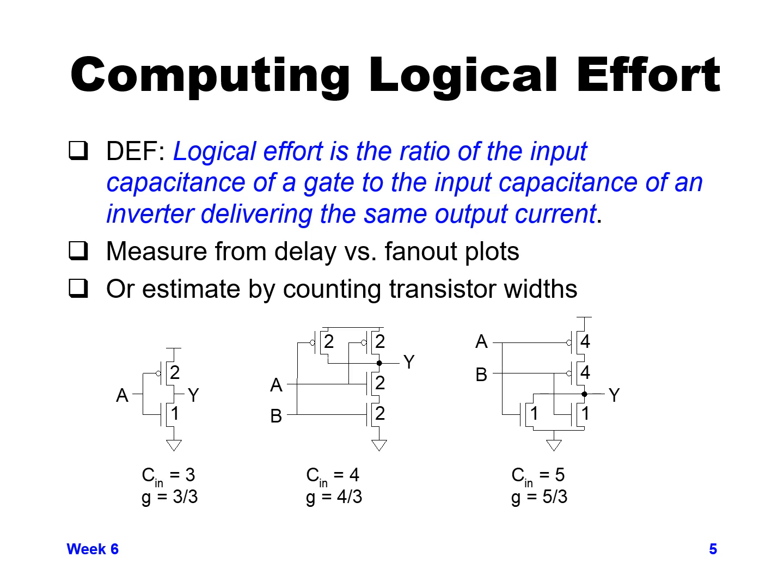So that's why the NMOS are twice as large, but the PMOS, since they're not in series with each other, each PMOS can drive independently to the output, and there's just a single PMOS between the output and the VDD or VCC, and so the PMOS stays the same size as what an inverter size PMOS would be. So they stay size 2.